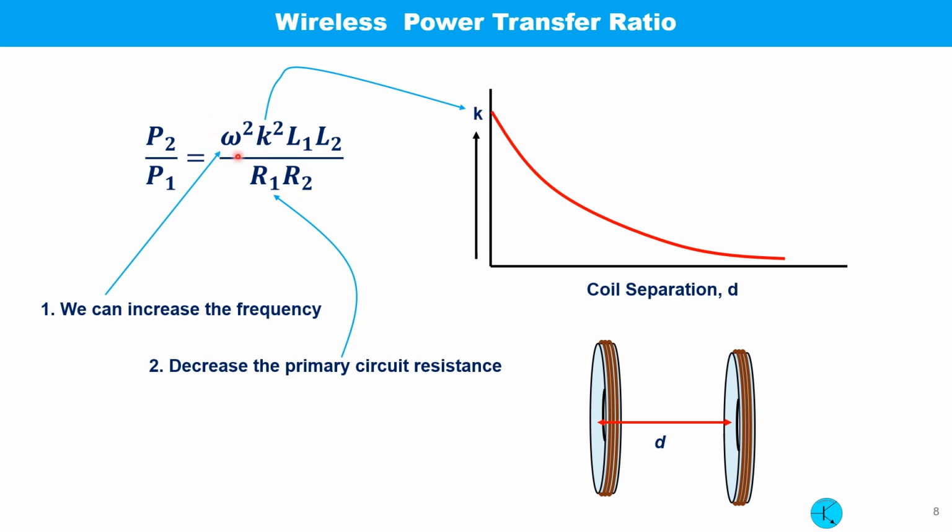So as the frequency goes up, another effect becomes very important, that is called skin effect. Higher the frequency, the electrons move to the surface of the wire, so resistance goes higher. So very much higher frequency will not give us any advantage. That's why several hundred kilohertz or few megahertz is the best choice for wireless power transfer.